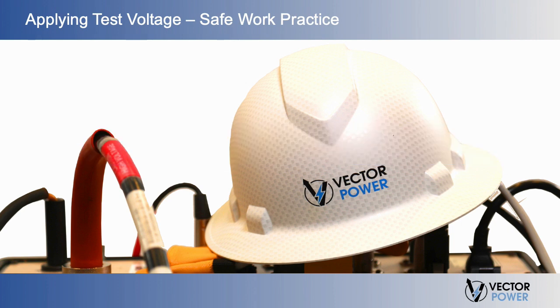Many people fear the electrical output of their insulation tester, which may be 5,000 or 10,000 volts. However, the instrument's current is generally limited to a few milliamperes and presents a relatively low hazard. The danger here is not so much the output of the Megohmmeter, but more the working environment. If the connected load is capacitive in nature, this can provide very significant energy when charged to high voltage by the Megohmmeter and can be lethal if touched.